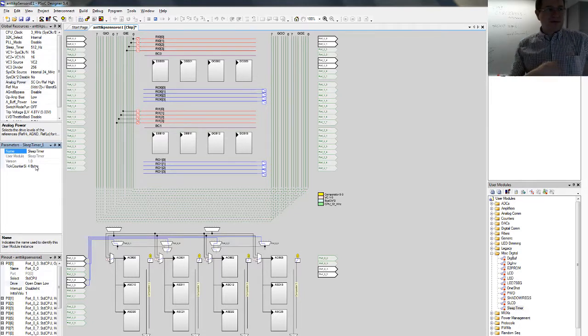The biggest number, 4 bytes, so that would be big enough. So it's 32-bit. Yeah, big enough for most applications. The real sleep timer divider is actually one of these global resources. For example, there you can select 64 Hertz. Okay. Now I have a sleep timer on my design.